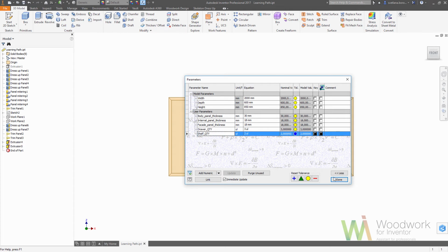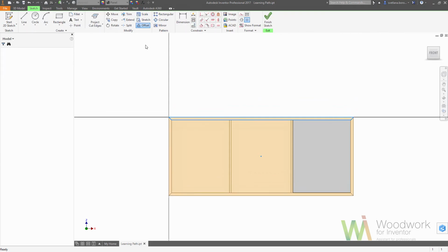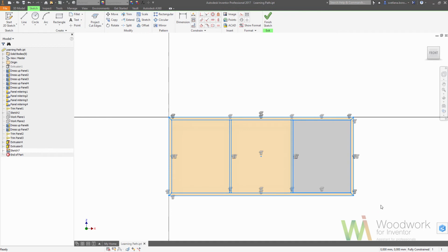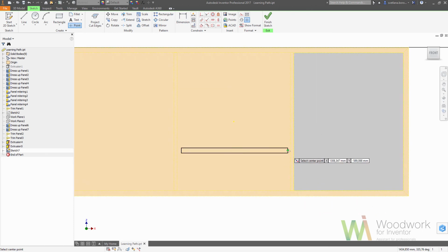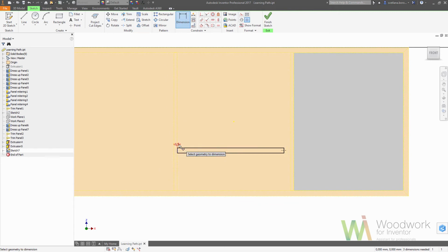On the skeleton, we need to create only one occurrence of the repeated item. So let's make a new sketch. Again, project the cut edges, mark this as a construction using right click, and here we can draw the shape of our shelf. Okay. Because we want to define the height, we are putting the midpoint on the edge, and as well we define the offset from a side. Okay, so those would be equal. We can choose the parameter by simply clicking on it.